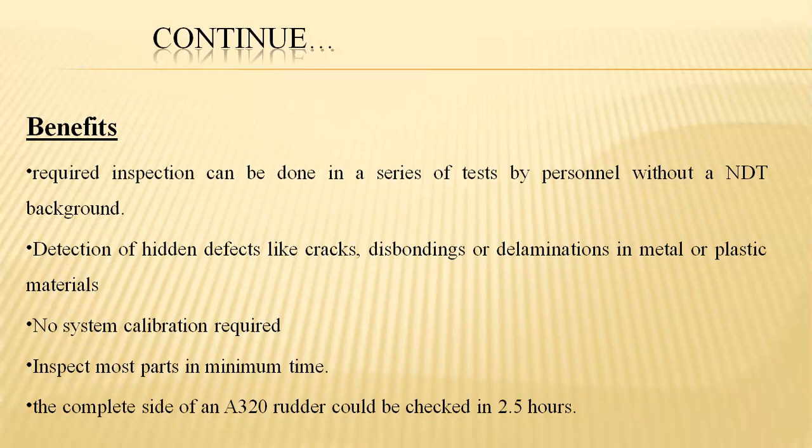Even hidden defects, such as internal cracks, disbonds, or delaminations in metal and its layered formations, or plastic materials, are clearly examined with this active thermographic technique.